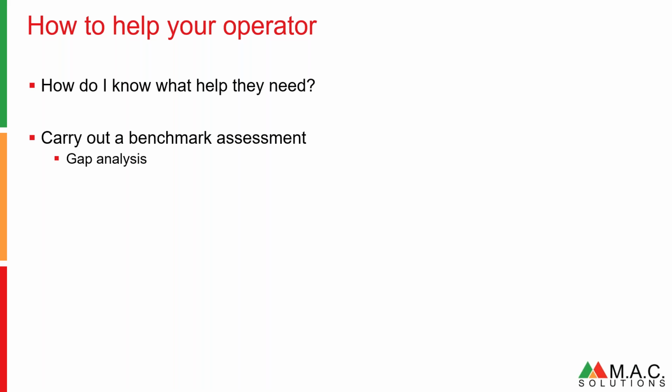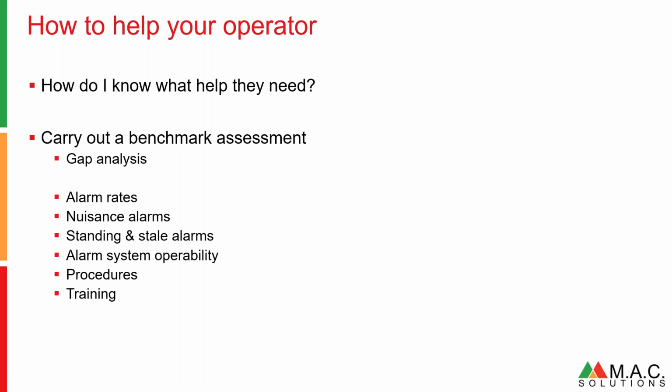Well, the first thing is to carry out a benchmark assessment, which is a gap analysis. Now, as an alarm management consultant, I'm naturally going to say, I can do that for you if you pay me some money. As part of that assessment, I'm going to identify things like alarm rates, nuisance alarms, whether you've got procedures in place, whether your operators are trained properly or not. I'll do a full assessment, take a couple of days on your site and write a big report, 30, 40, 50 pages perhaps, with prioritized actions and recommendations to help you comply with legislation if necessary, comply with the standards. I can do that for you. Naturally, I'm going to say that.